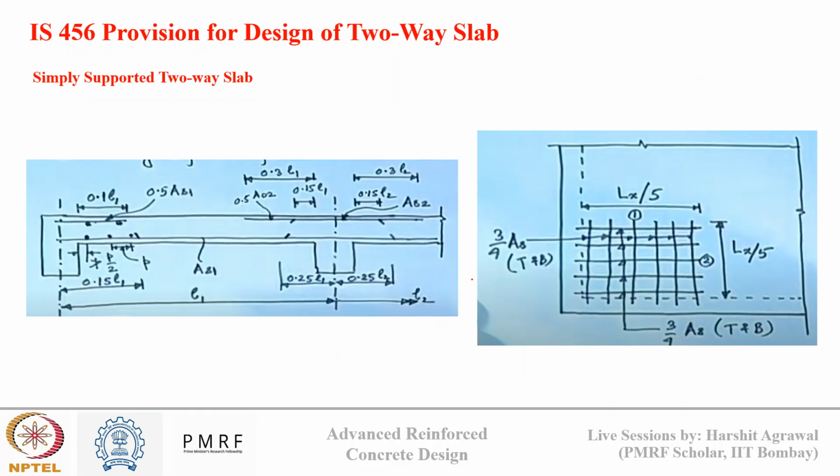Okay, here in the first figure, you can see how reinforcement detailing is done. So if we have Ast1 reinforcement as tensile reinforcement, 50% of Ast1 will continue till the support. Remaining 50% we need to carry in the compression part within a distance 0.1 L of the support.